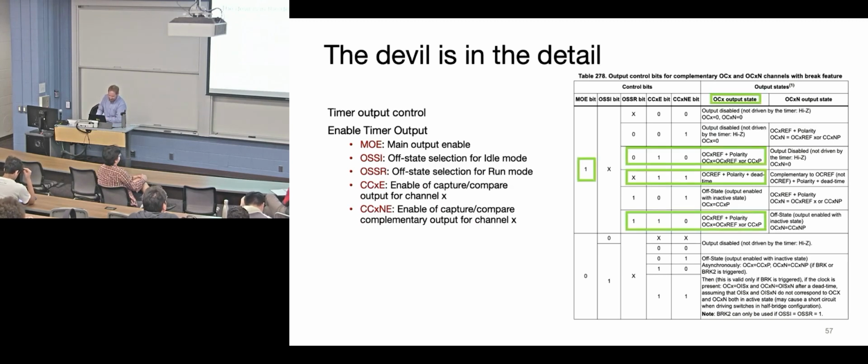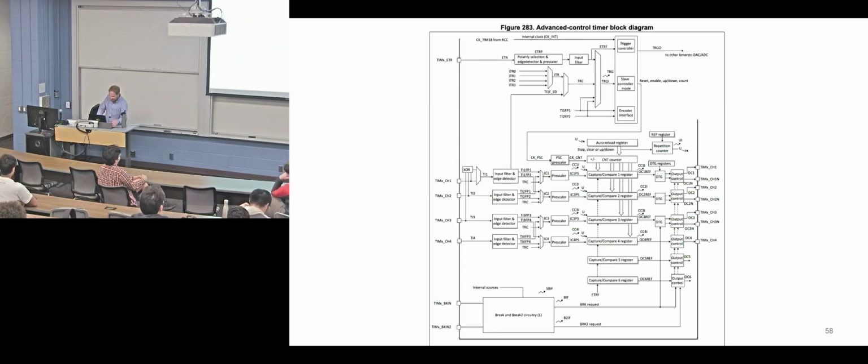You have to enable the main input. There's a bunch of idle and run modes you have to set. You've got to set your capture compare registers. Those we've already covered. And then just for you guys to think about, this is the block diagram.